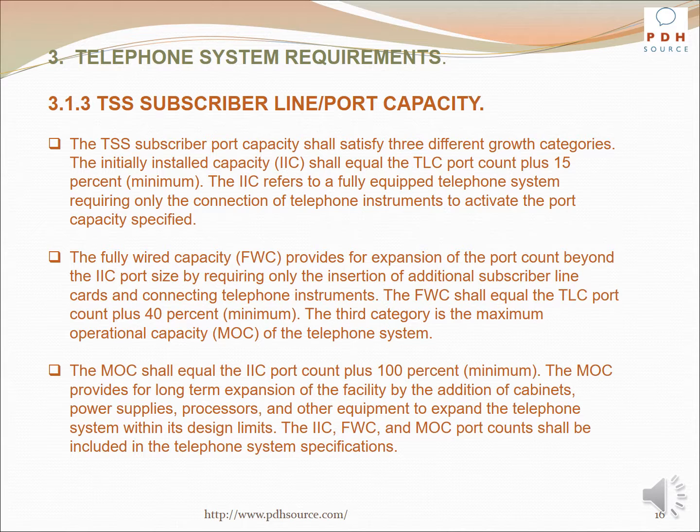The third category is the maximum operational capacity, MOC, of the telephone system. The MOC shall equal the IIC port count plus 100% minimum. The MOC provides for long-term expansion of the facility by the addition of cabinets, power supplies, processors, and other equipment to expand the telephone system within its design limits. The IIC, FWC, and MOC port counts shall be included in the telephone system specifications.